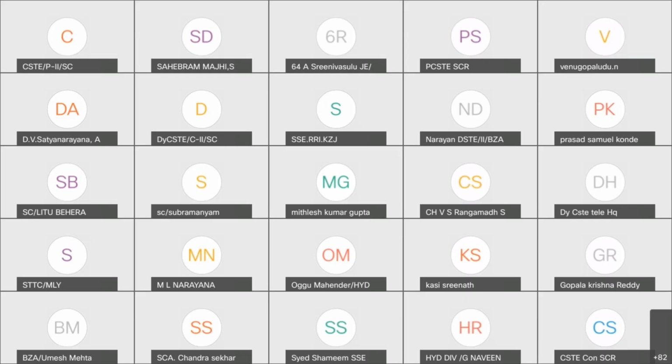The second problem that I have observed is the detection rods which are connected to our slide. The hole given by RDSO is very big, sir. Because the RDSO diagram has given a very big hole to the lug, if we fix it in our detection slides there will be a lot of play. Previously, without the P clamp, when it was fixed with the tongue rails, that diagram was given. But now in the recent diagram, which is with the P clamp, they have not changed it. The present diagram shows the lug having a big hole, and if we fix that in our detection slide, there will be a lot of play, sir. These two things I have observed, sir.